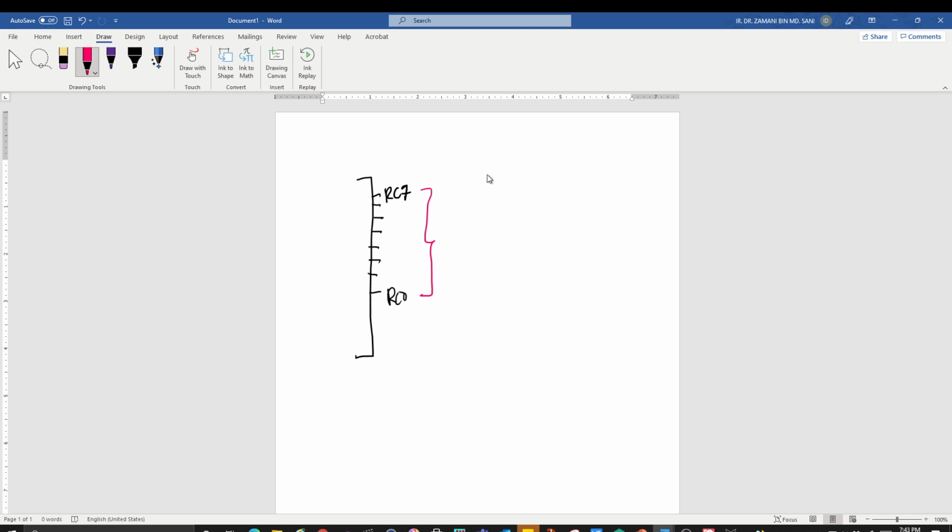Then when you put 0B, this is to show how you want to set in terms of binary, which is 1 or 0 only. So 1, you are going to set it as your input, and 0, you're going to set it as your output. This is just to set the mode, because if you have this pin, it must know that it must be used as what.